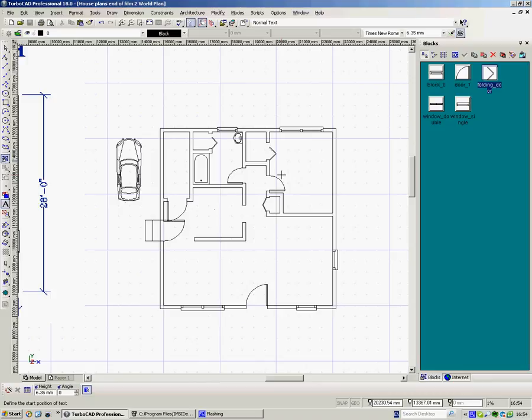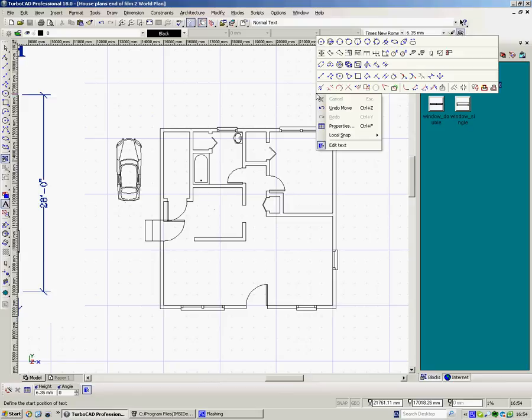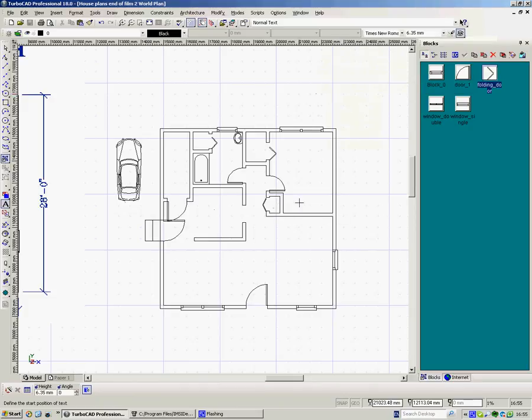The other thing you can do in here is where we've got double line tools, you can have parallel double line tools, so that if you wanted cavity walls, they'd be very straightforward to draw as well. Okay, so all you need to do there is to look in the manual under double line tools, and the last icon in the double line tools is called parallel double lines.